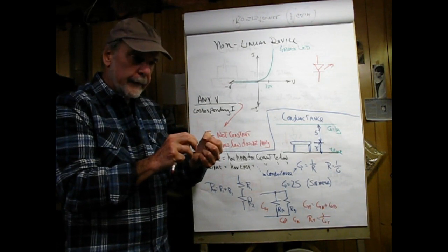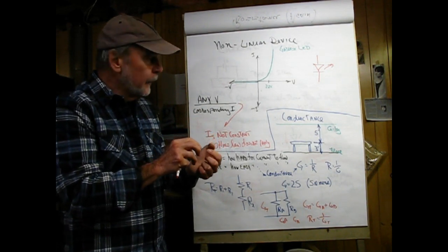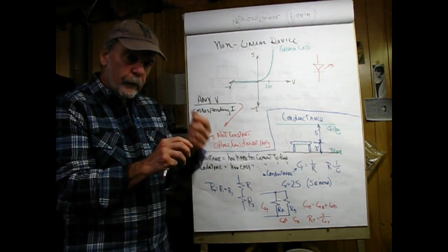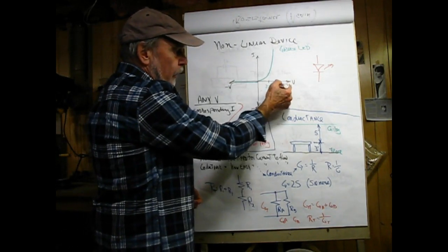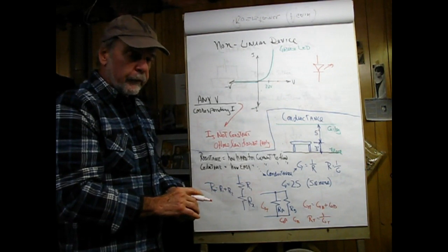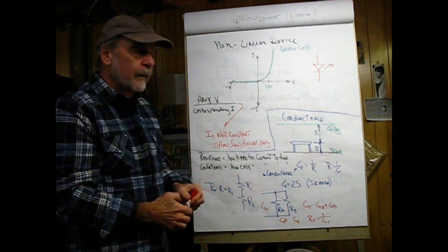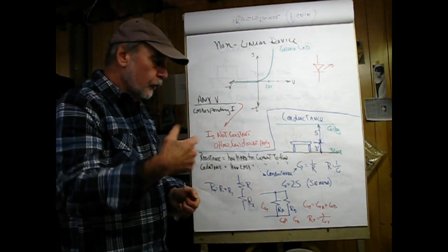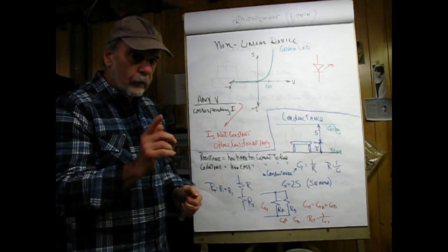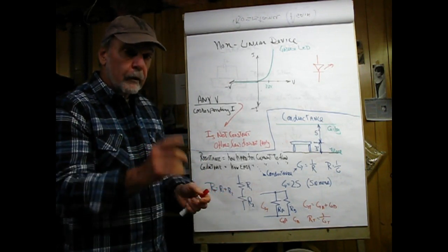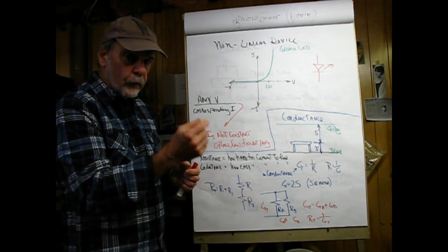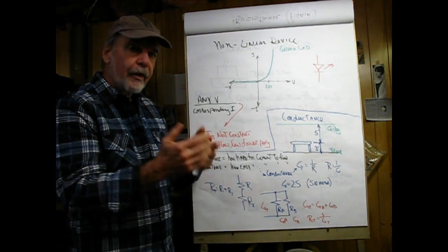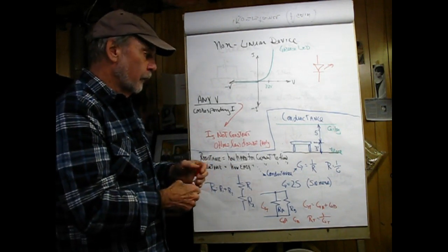So the core of that, the engine under the hood, is a blue LED. And blue is a higher frequency of light, which means it's more energy. So its value would be out here somewhere between 3.3 and 3.9 volts. Hence, if you have an LED Christmas tree string, the lights you look for first, if your string is out, are the blue lights. Because the current is constant and the voltage drop across blue is higher, they actually run hotter than the other colors of light strings.